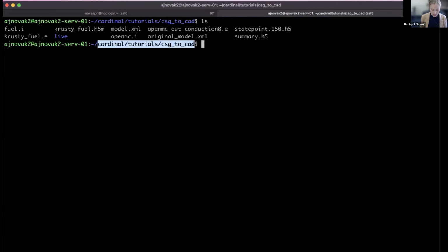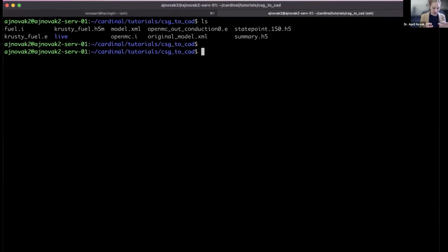So I'm going to start by walking through the input file we built to solve for heat conduction. So let me maybe describe the structure a little bit first. We're going to have two different input files, one for each physics. For the problem we're solving today, we have heat conduction physics and neutronics. So we're going to have two different files. Each of them are going to solve their own set of equations and pass data to one another. They're going to be coupled iteratively.